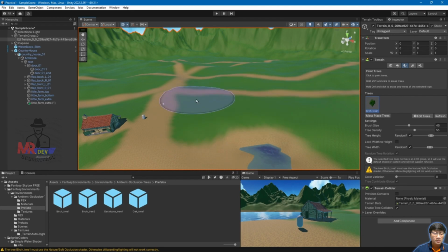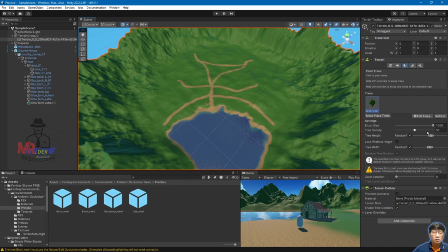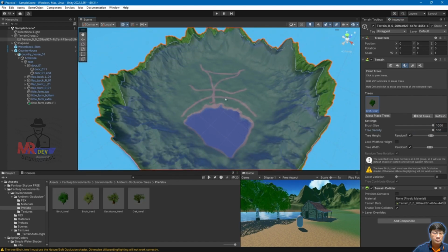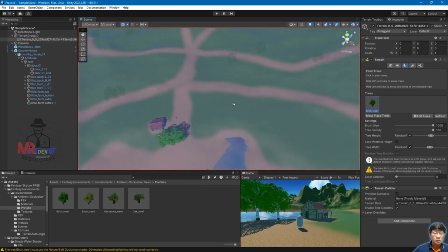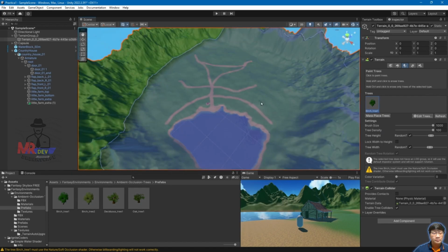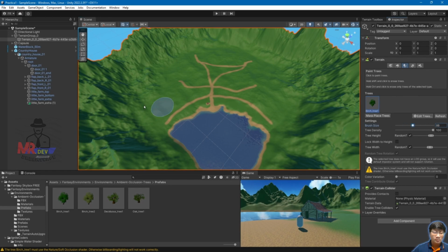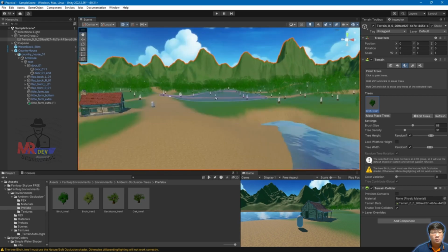Well, now, for example, if I want to place lots of trees throughout the terrain, the brush could be very large, with a very high density. And I click on it and start painting. But it fills up with a great width of trees. Another way to do it is to put here a smaller brush with a very high density. We went down the stairs and filled everything with trees, didn't we? That is one way of filling the stage with trees.